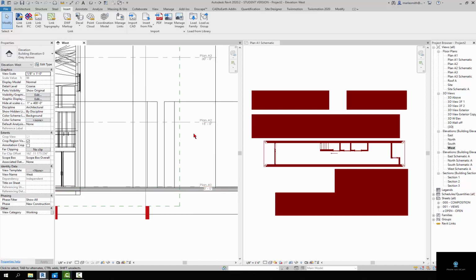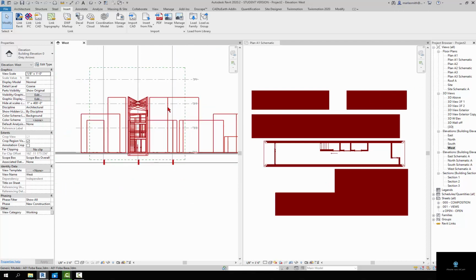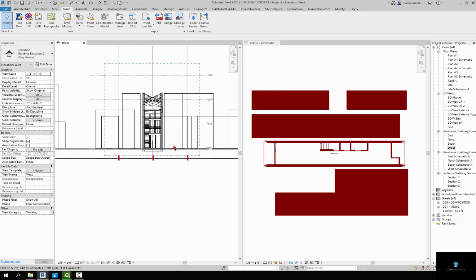This is called a level, and these levels are what determine how the floor plan is being cut. So what it's doing is it's going from that level, going up 4 feet and cutting that model in half, just orthogonally and looking down on it. And then we have some visibility settings over here. You can see that our levels are not in the correct place. The levels should really be at the finished floor, and these two are not. Remember, this is a template that was set up, and you have to go in and do some adjustment.